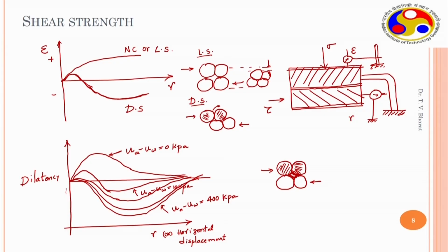So, it reaches a peak value, and once these surface tension bonds are broken, it exhibits a strain softening behavior. Therefore, it overcomes the surface tension forces in the soil pores, and exhibits a dilation behavior similar to densely packed soils. This is a very interesting behavior that we understand from such tests.